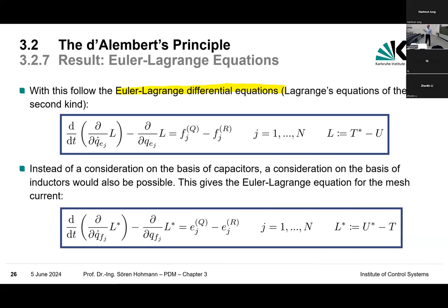On the disadvantage side, you find something that you have to know, the coupling via the non-redundant coordinates. So beware of this. Here, you don't see any kind of tilde with which I denoted the redundant coordinates. As you know, some of the storage might be coupled in an algebraic way. So the answer is, if you know a set of non-redundant coordinates of the system, namely Q, E, J, then everything is fine. We just collect the storages, do the calculations, and here we have it. Basically, that's it. With that, we have our equations of motion, and we already know they are governed by an energy-based principle.